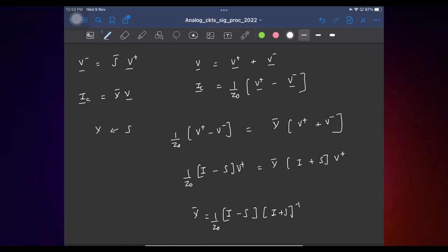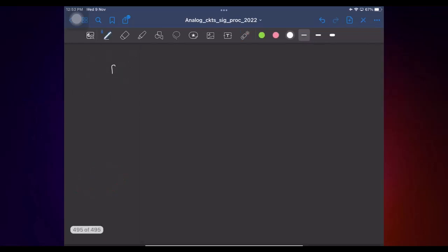And you guys know that for Y parameters, if the network had only R, L and C, Y12 was equal to Y21, right? And you know the relation between Y and S parameters. So take it as an exercise and try to find what this means. Now you know S parameters are S11, S12, S21, S22.